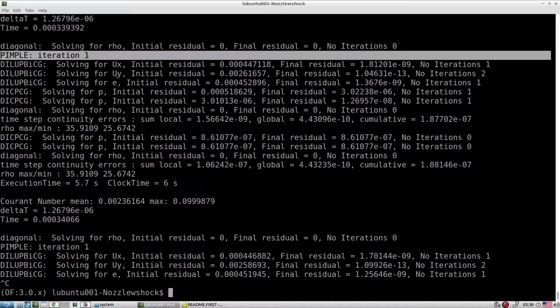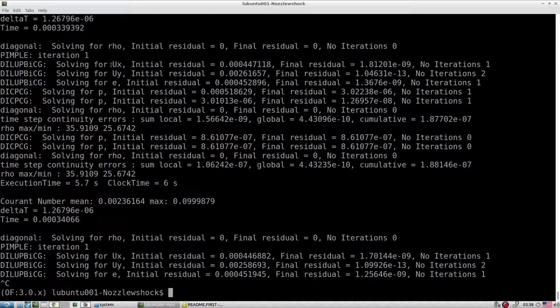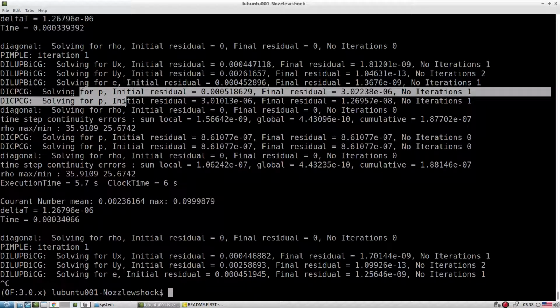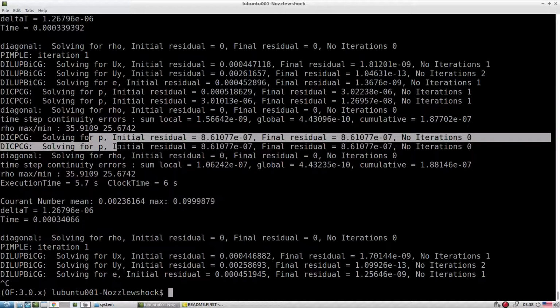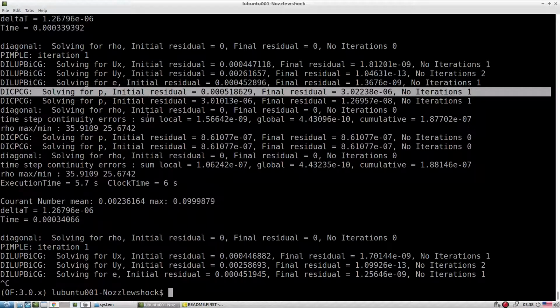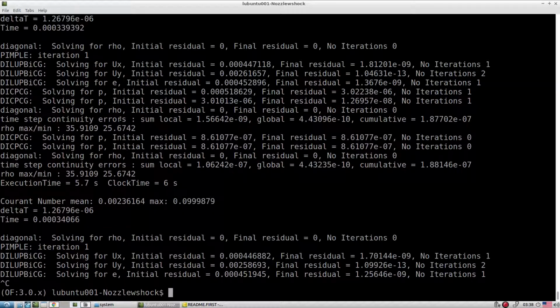And then we have a predictor, the energy equation. Then we have a corrector step. We specify the two inner correctors and one orthogonal correction. So that's why you are seeing all these different entries here. So this is what you can see in the output.